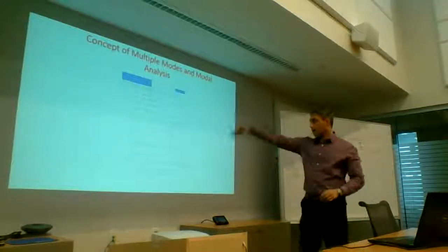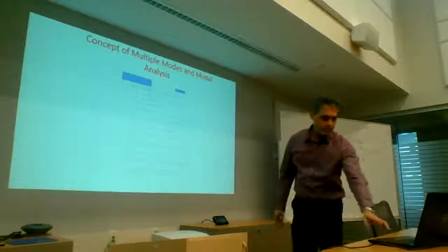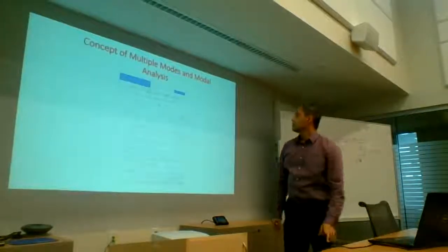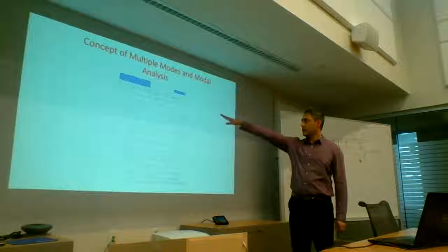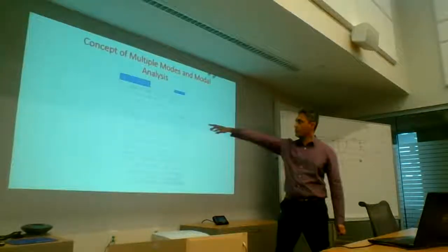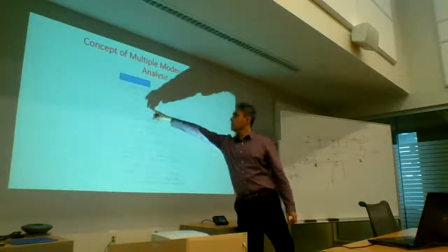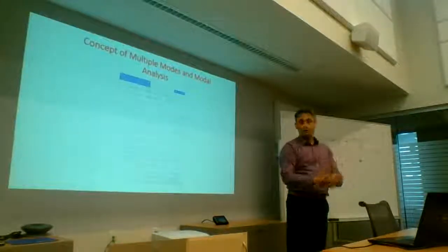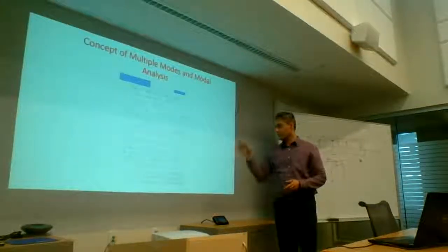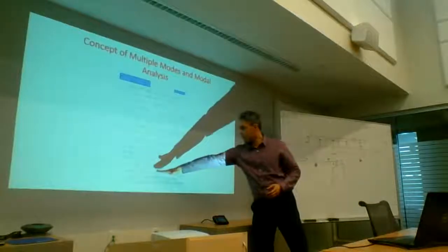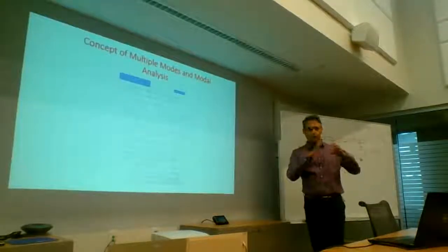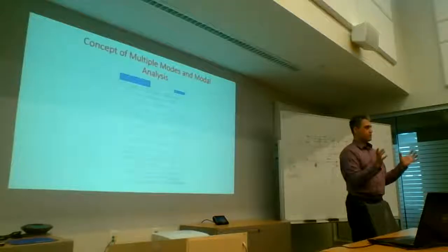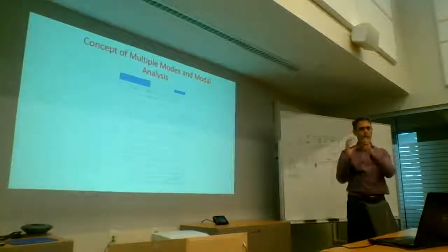And when you go through the mathematics of it, you find that after you've applied modal orthogonality, where because the modes are orthogonal, mode number n doesn't do any work in going through mode number r, those terms are zero, they cancel out. And at the end of it, what you're left with is decoupling of modes. So for each mode, you get one equation.